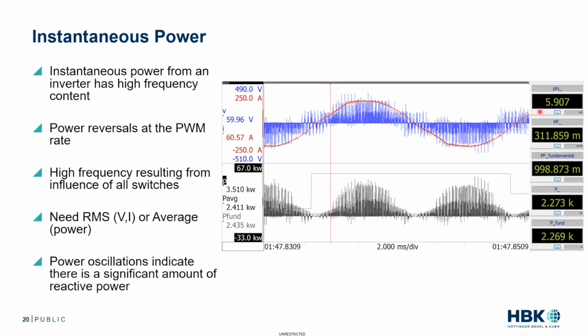So if we look at the calculations, this is based on, I think, a 200 kilohertz filter rate, so a 500 kilosample sample rate. Our phase angle, again, this is of the fundamentals, because that's really the only way to calculate it, is 5.9, so a relatively low phase angle. But our power factor is 0.311, because this is power factor calculated with all those harmonics. Power factor of the fundamental is 0.998. So what's the difference here? The difference is switching frequency.